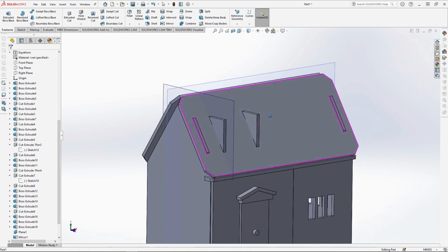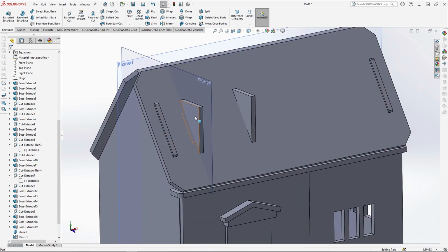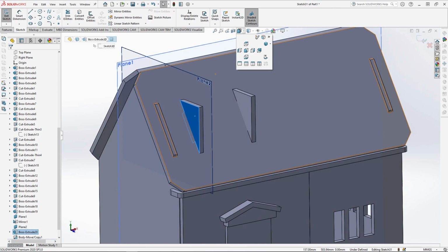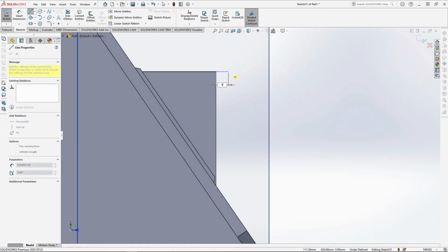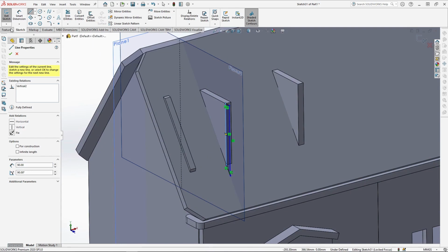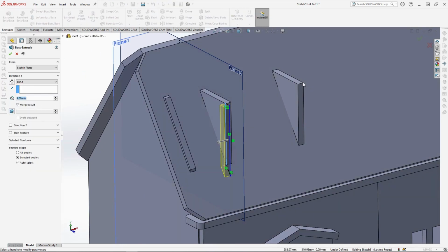To create the front, I'm going to extrude the profile from the side. Sketching onto the side of the window box, start from the top corner of the line and go out by 9mm, vertically down to the roof edge and back along the roof here to join it up. Extrude this up to the end vertex of the other window box side, ensuring that it's unmerged.